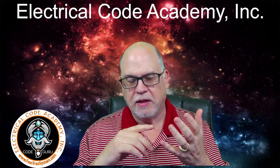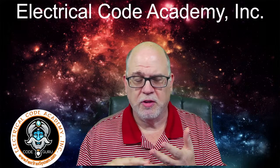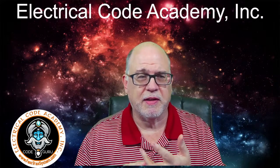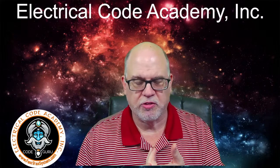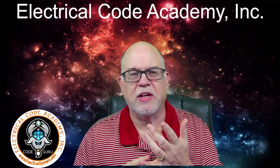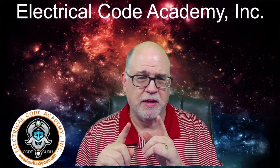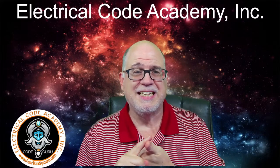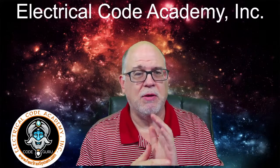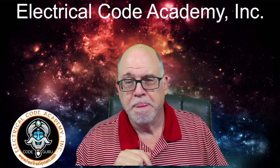In other words, what code reference sizes conductors, feeders, feeder overcurrent protective devices, short circuit and ground fault protection, branch circuit short circuit and ground fault protection, understanding the table for 430.250 and when you might get something on an exam and you've got to be careful, and overloads. So somebody did submit a question for that, so I will be walking you through the code book for that. That'll be part of what we do as well.